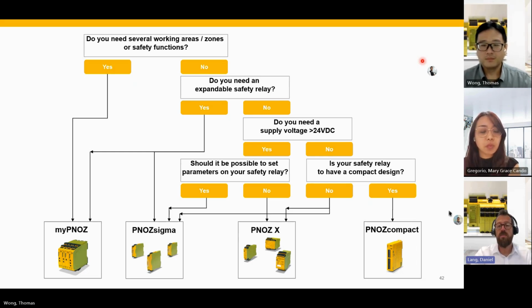And then for the output, you have safety relays which are non-delayed and delayed. I cannot tell you any number, but let's say these are the four types: OSSD or non-OSSD, and delayed or non-delayed output channels. So there is a big variety. We have seen that there are some safety relays which are only capable of e-stops, and we have seen there are safety relays which are capable of everything.